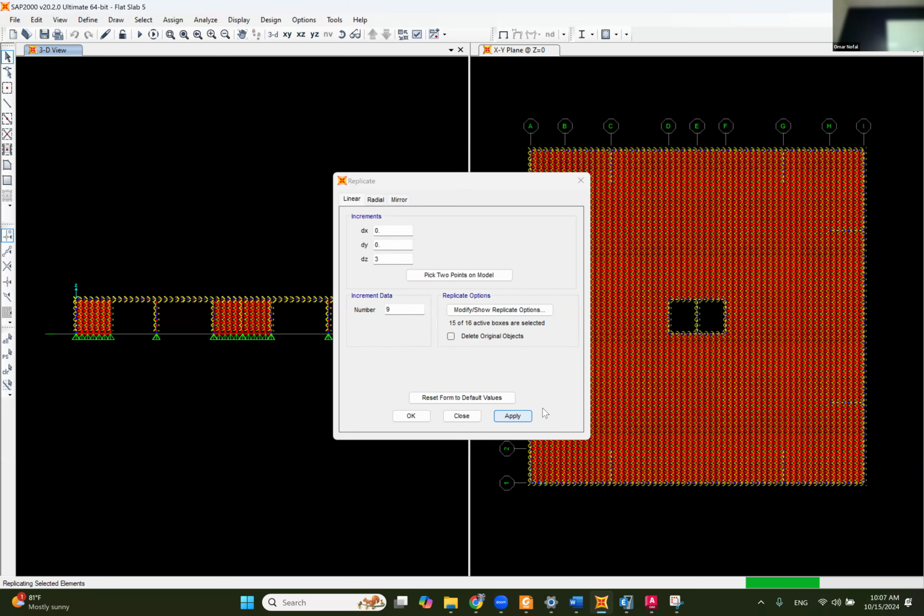So hinges are only at the base floor, where the foundation is. Any other floor is stable based on the column below this floor. We already have this column. So if I select the whole model with the hinges, that means that we somehow make the floor not moving. But the floor, if it is hit by an earthquake, is going to move. Okay, so we only put boundary conditions at the foundation level where we have the foundation.